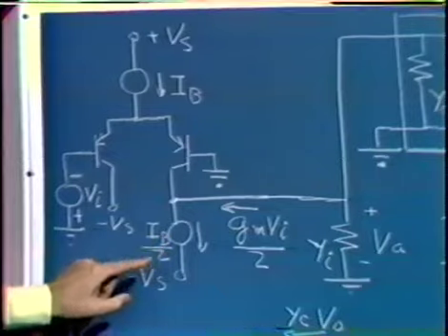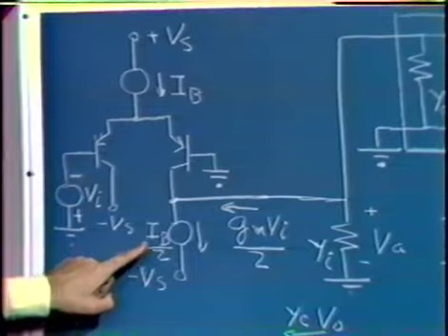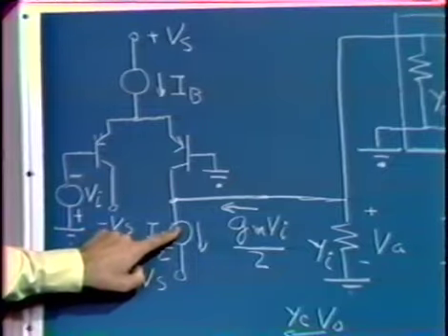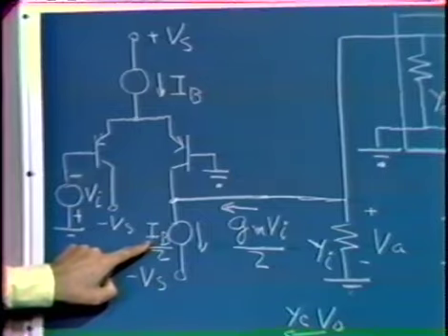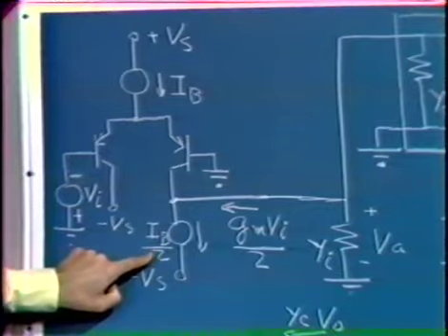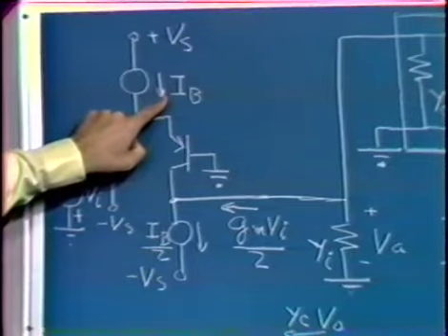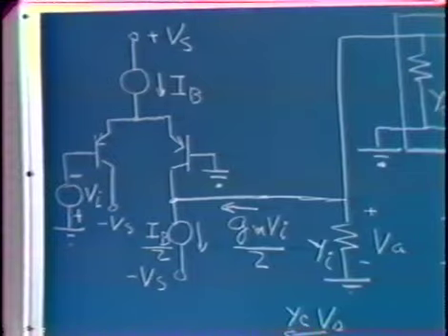And again, in a little distortion of reality, but one that does lead us to the correct result, I assume that the first stage is loaded with a current source, in fact, a fixed magnitude current source. And what we generally do would be to connect or select this current source to have a value 1/2 of the current used to bias the entire first stage.